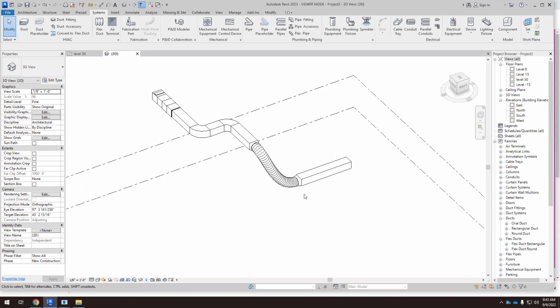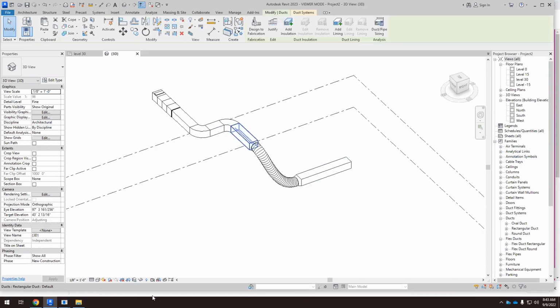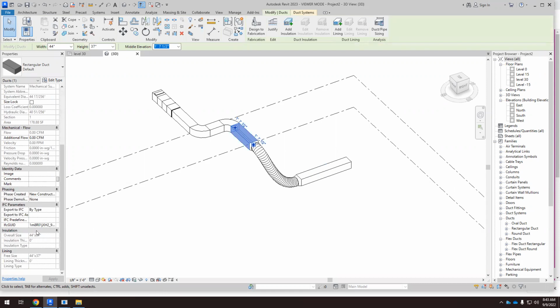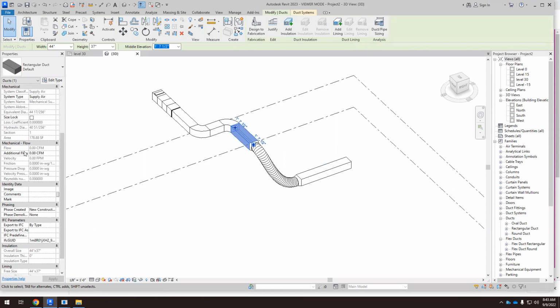No, that's the beginning, and then we have to check all the parameters that when I was a student I had to calculate by hand. And then, okay, so what's the size of this? If the size of this is 12 by 12 inches, the airspeed has to be, I don't know how many feet per inch. And then it was a nightmare, okay? The airflow is this, but here you have all this information. If you click here, you have the airflow. We have not considered any airflow here. You see that it's 0, but you see that we can change it.